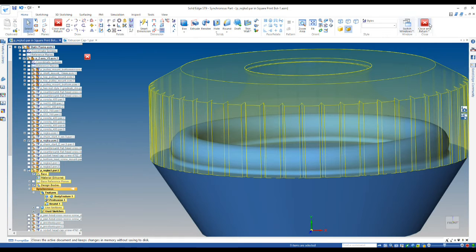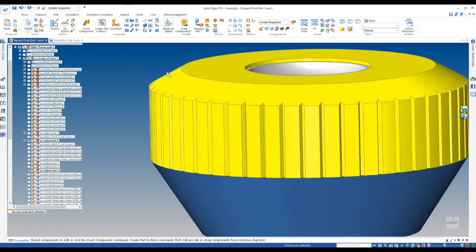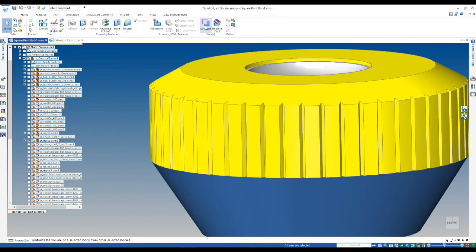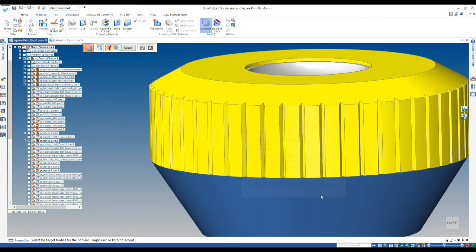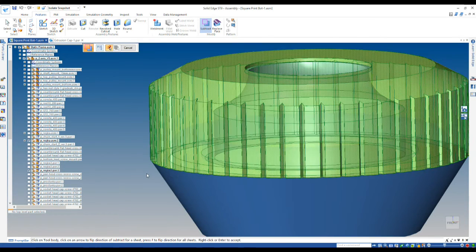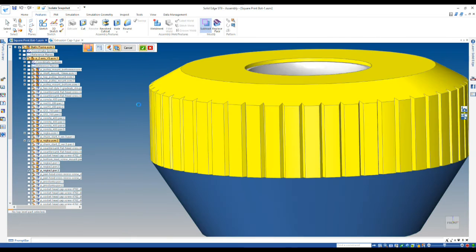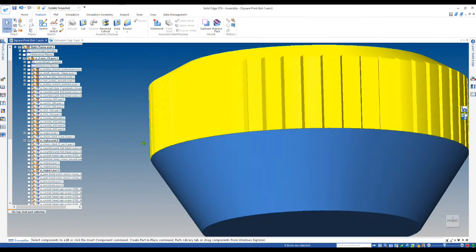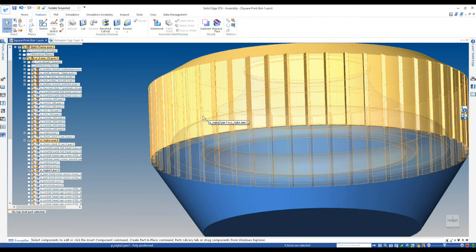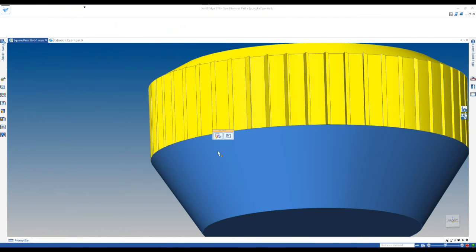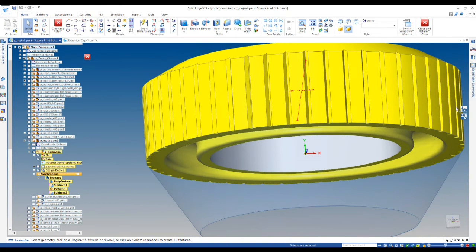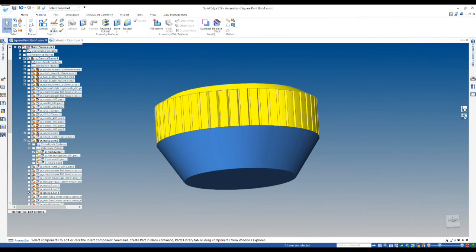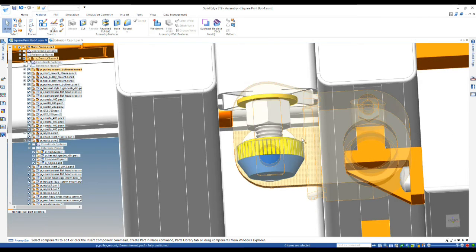Close that part, edit the top part, because now obviously I have to put a groove in the top component. Now we have a unique feature when we're subtracting. We can subtract and create matching threads. Obviously there's no thread here, but I just subtract the foot from the base, and you can see I now have a nice matching groove. So I'll just close out and undo my isolate, and I've got all my parts back. Just nice and quick to work with.